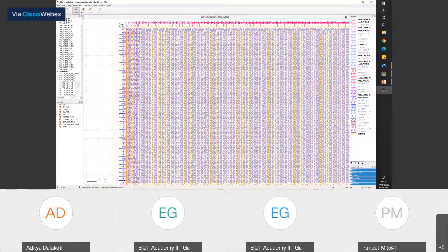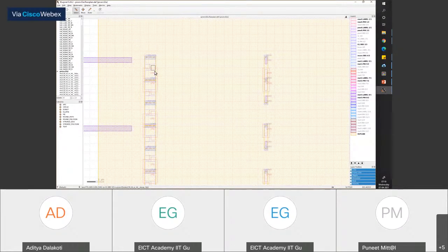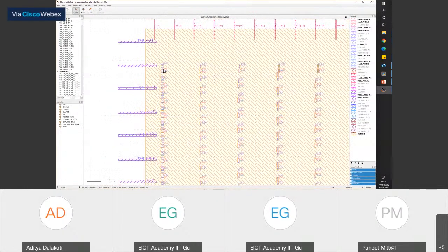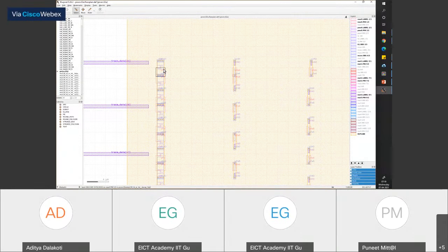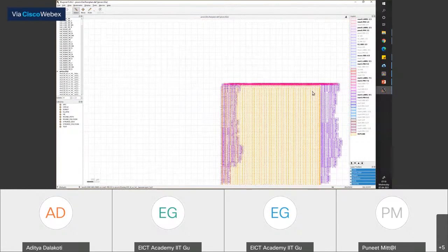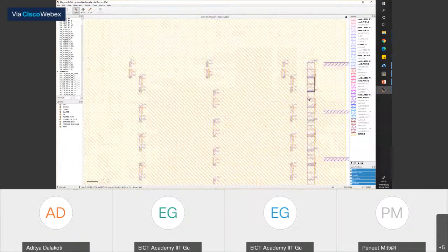So basically what these are are tap cells and decap cells. At the boundary, there are decaps, and overall in the whole design, there are tap cells distributed. These boundaries are decaps, the rest of them are distributed tap cells. How they are actually created depends on the script. There are a few environment variables to change them as well. You can explore them in your own time.